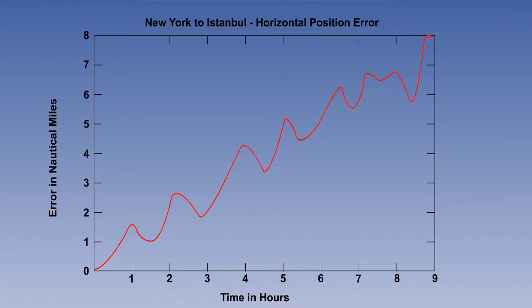Unlike our earlier diagrams, which were idealized, this is an actual plot of INS against GPS on a test flight. The pattern can be clearly seen. There is a basic ramp increasing at approximately 1 nautical mile per hour, with a 1 mile Schuler oscillation superimposed on it.